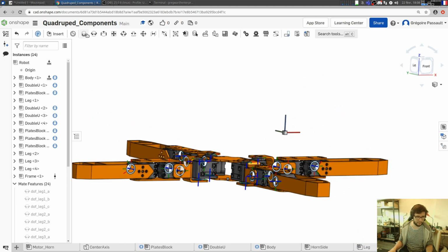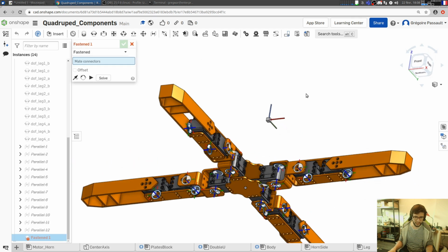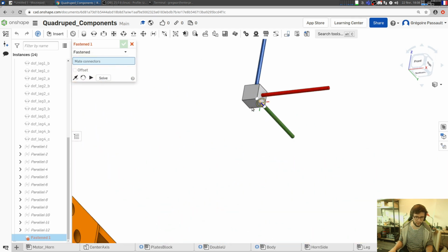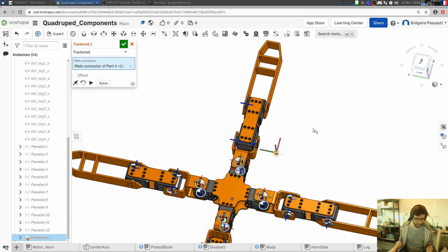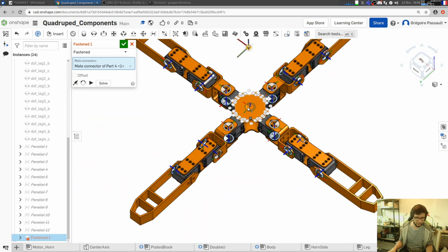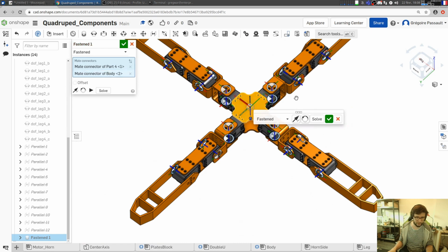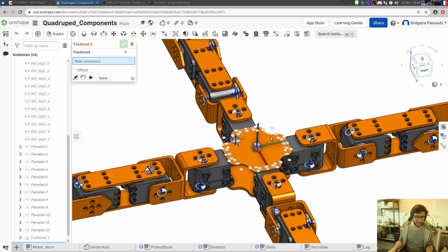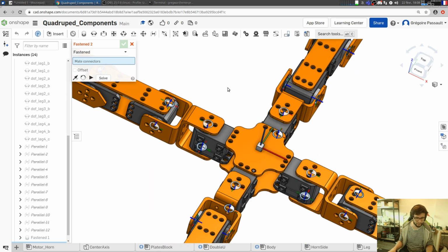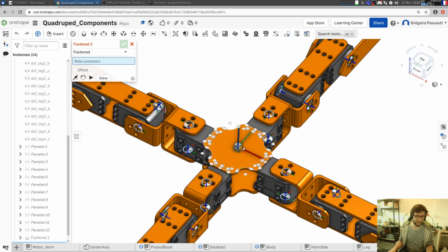You can use a fastened mate. Just click on the child first, always, as usual, just for the joint. And the parent will be, suppose, the body here, if I want to be able to track my body. So again, this frame can be any kind of assembly. Here it's better to have something visual because you can see the x-axis, the y-axis, the z-axis clearly.